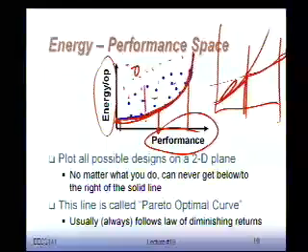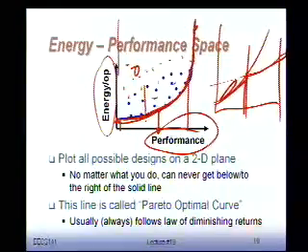It's that being extreme never pays off. Let's say if you look at this curve here, I might go for the maximum possible performance. I'm going to be here. Right? And I'm going to really push hard, big transistors, I do everything in the book to get the best possible performance. You see that the cost in energy is huge because this curve is almost flat here. So just getting a very small improvement in performance, going from here to here, is going to cost you dramatically in energy.